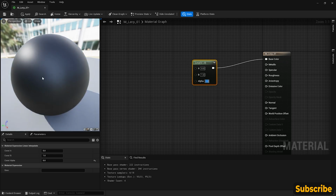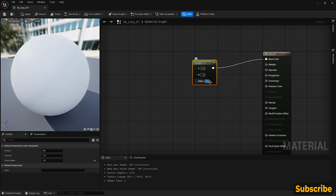And again, we should see the output 0 at 100%, because this is saying at 0%, show me whatever's in the A channel. And at 100%, show me whatever's in B channel. So again, if I type in 1, it is the equivalent of 100% the B channel. So now I'm seeing 1 as white.